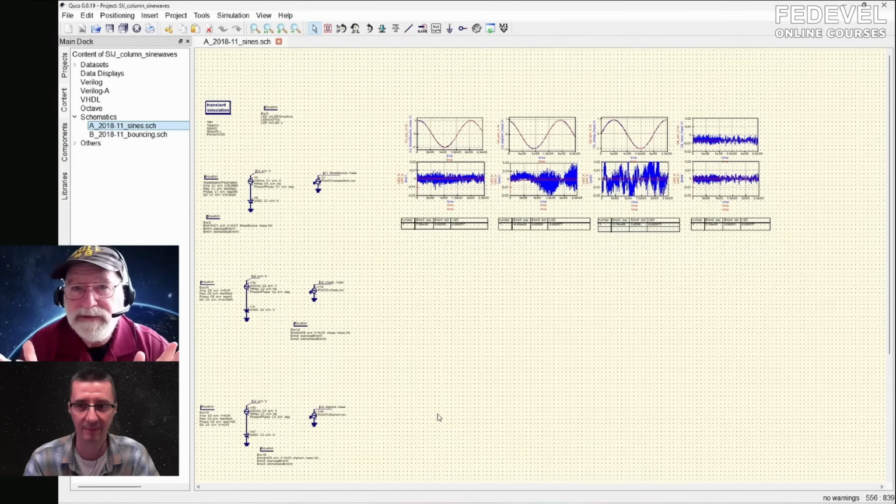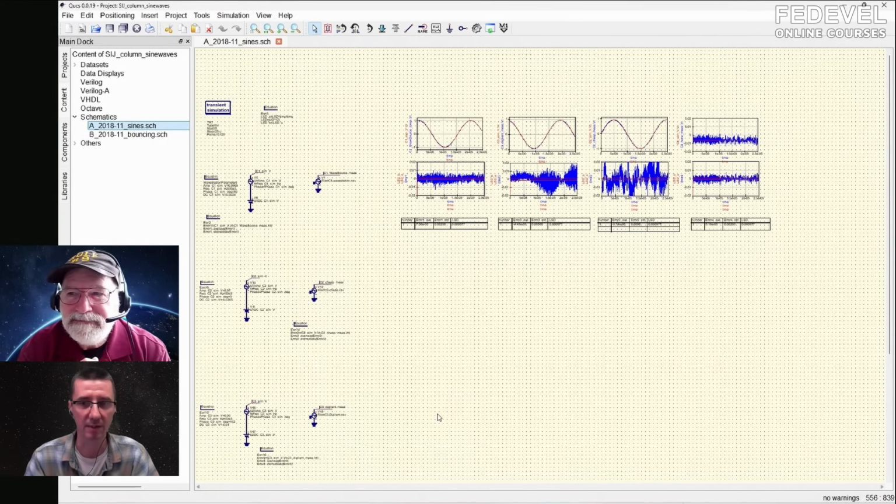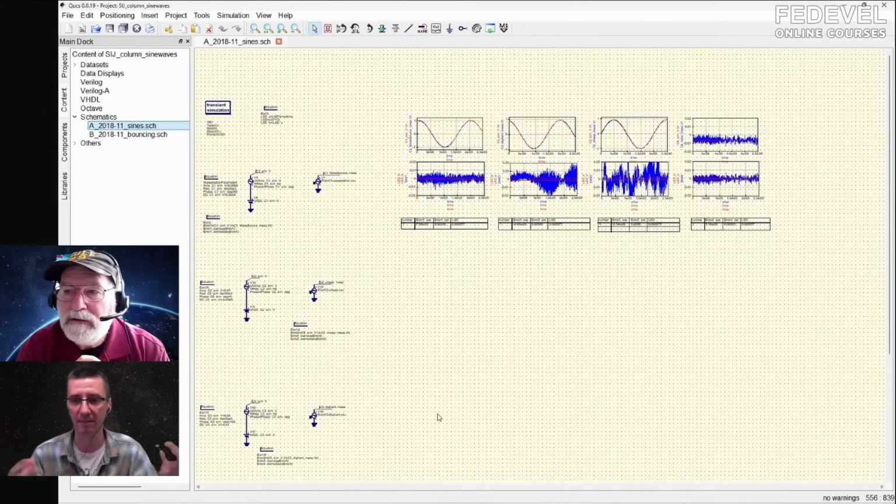It's a SPICE simulator. And so anything you can do in SPICE, you can do with this tool. And it's especially valuable for signal integrity because it also understands S parameters, and you can simulate and view S parameters as well. But we're not going to talk about that one today. S parameters mean, for example, from an existing PCB measurement, we can generate an S parameter model, and then we can simulate our own PCB in this software.